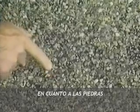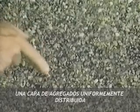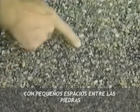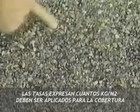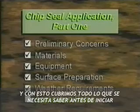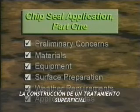As for the chips, the rate applied should leave the surface like this: one layer of chips evenly distributed, with small spaces in between. The rate is expressed as so many kilograms of chips per square meter of surface covered. And with that, we've looked at everything you need to do to get ready for chip sealing.